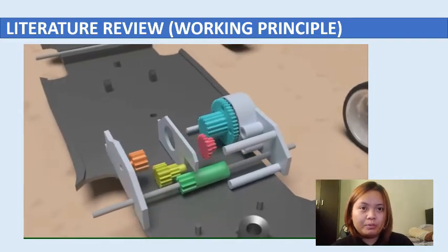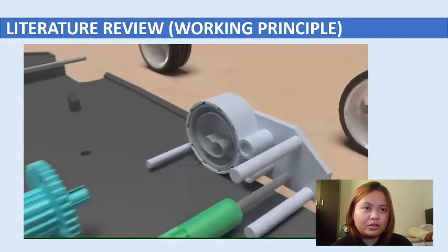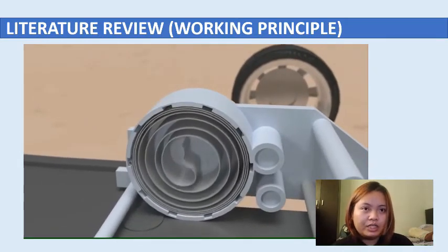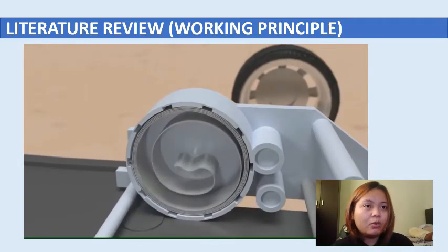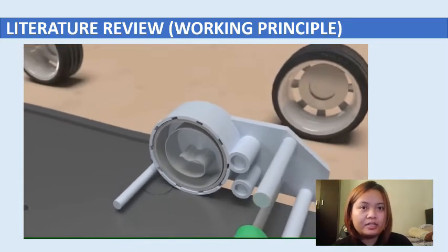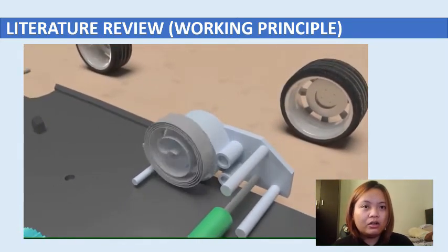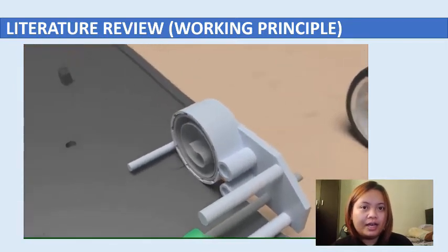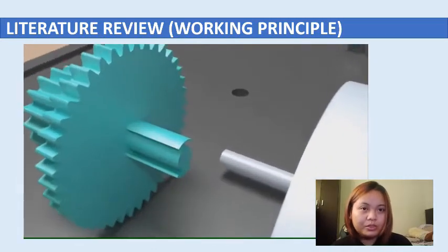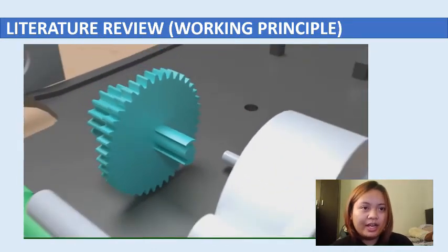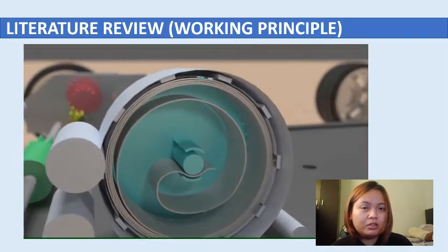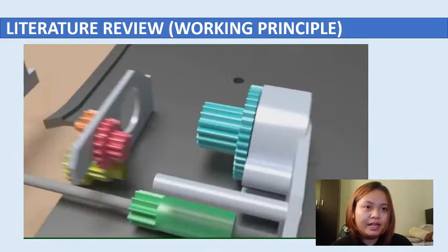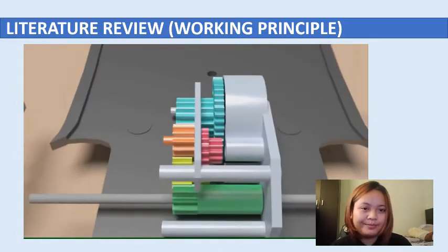As per the working principle of the pullback car, behind the biggest gear there is a stored twisted piece of metal called a torsion spring. The more you twist it, the more energy is stored inside. Once released, it quickly unwinds and the car is propelled forward. Here on the large gear with curved extension and feet around the center of the spring, as the gear turns, the spring does too. Pulling the car backwards activates an internal spiral spring, and this is possible because the motor inside is clockwork. This is called the gear train, and it is what causes the spring to wind up.